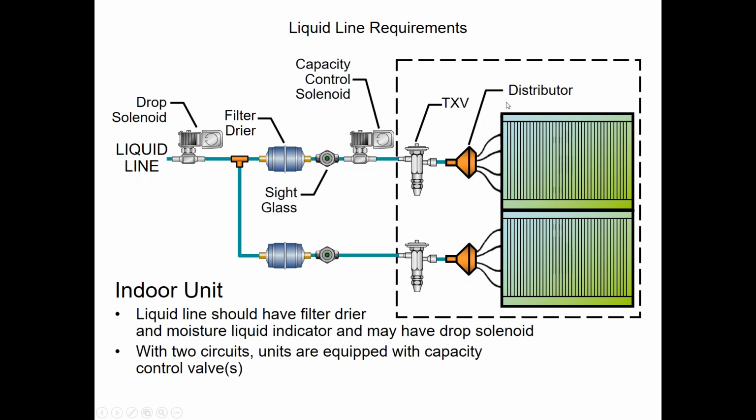So it was a way of managing refrigerant on the low side, so we didn't have flooded starts, and we had actually a little increase in capacity because we had an instant liquid seal at the expansion valve, so the liquid was literally right here and ready to go. So it didn't take 5 minutes run time to develop your refrigerant pressure differentials and get a good column of liquid in the liquid line.